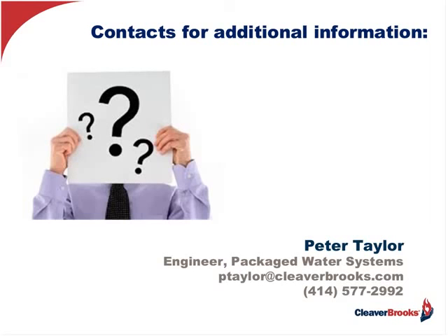Now, the other thing I want to make mention of is that every valve has a classification. It also has a pressure and a temperature rating. Make sure that you're not just looking at the pressure. That could just be hydrostatic pressure. It's got to also have the corresponding temperature rating as well. 100-pound steam is 338 degrees, for instance.